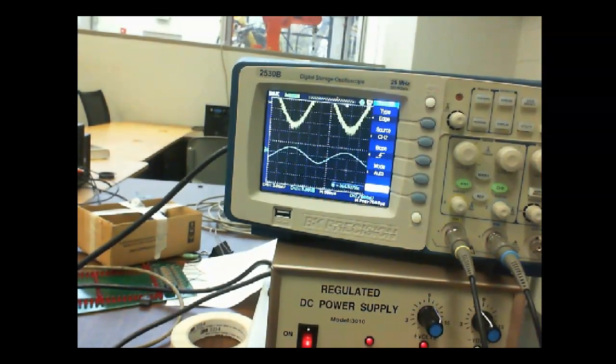So if I bypass it, we get extremely high gains, but we sacrifice input impedance. The input impedance drops way down. If we don't bypass it, we get a higher input impedance, but we can't get really high gains. Does that make sense? Y'all see the circuit?